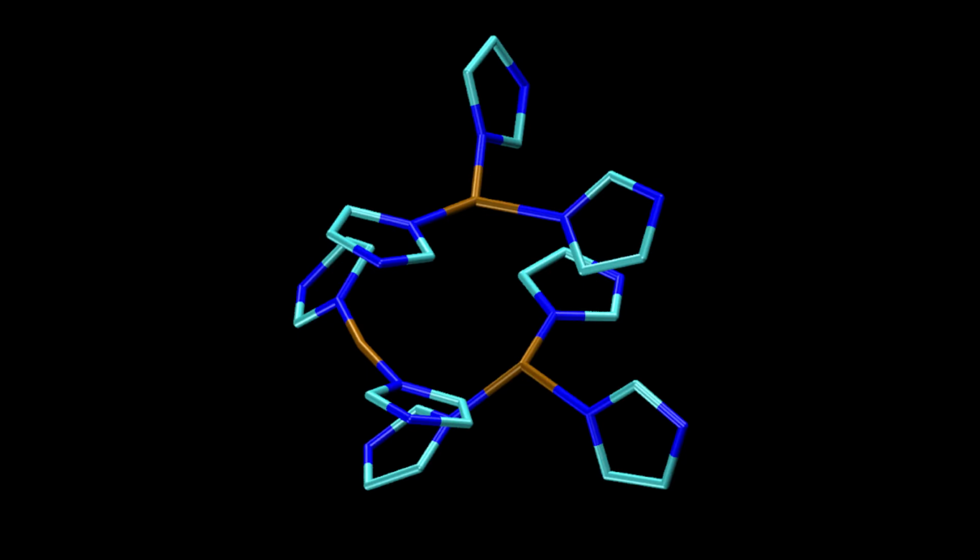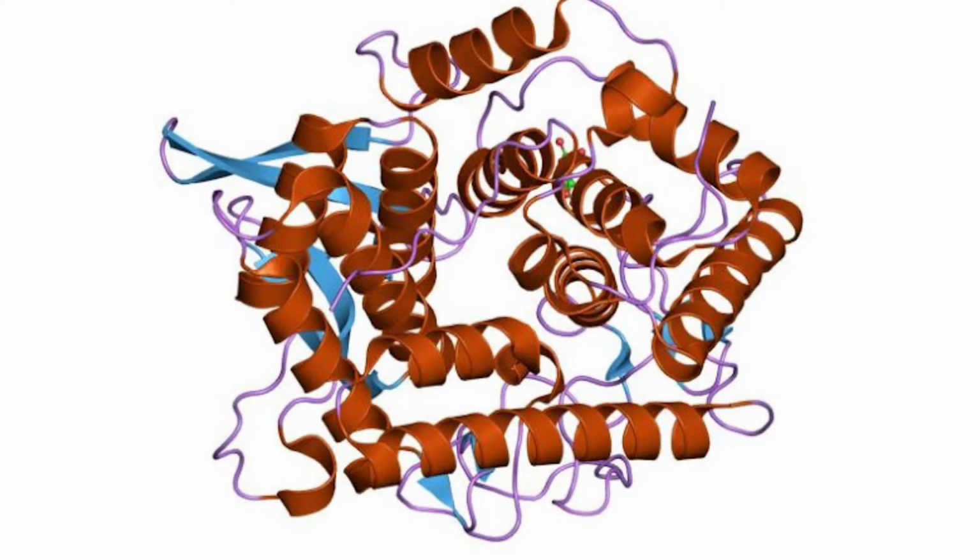Biocatalysts that are proving to be very useful in these applications include the following. Laccases. This class of enzymes can remove lignin from cellulose and wood without the need for harsh chemicals. These enzymes break down the lignin, leaving the cellulose intact. Xylanase. Treatment with this enzyme enables manufacturers to reduce chlorine consumption by 15–25%. This enzyme is used in bleaching procedures in which chlorine is completely replaced with chlorine dioxide or non-chlorine chemicals.